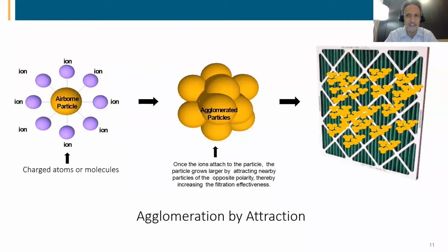We are opening the sail on the very small particles. We are making them bigger. We are exposing more surface area to lower velocity air in the space. That lower velocity air can now transport those particles back to HVAC system filters that before we were never seeing the particles. And because the particles are bigger, filters can be more effective at extracting them from the airstream. It's a pretty simple concept.